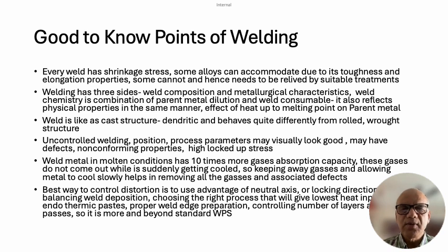So we have to be very, very careful in keeping all our gases as low as possible and have sufficient time for cooling, so that these are driven away between solidus and liquidus, so that we land up with no defect.